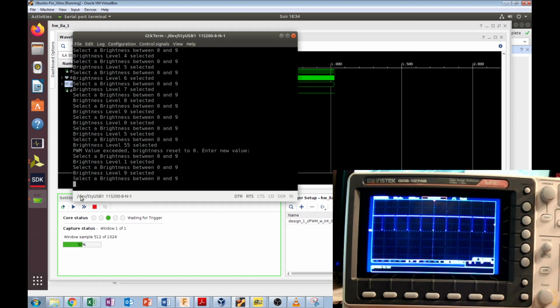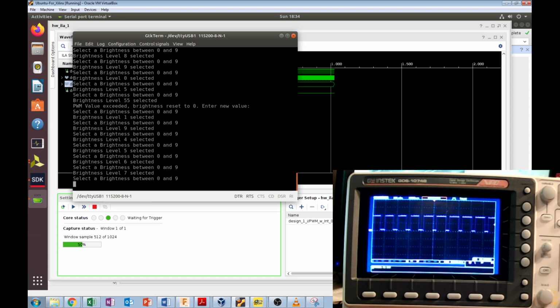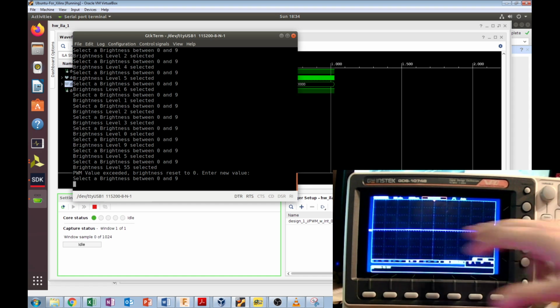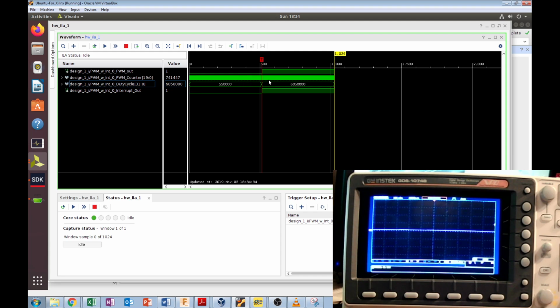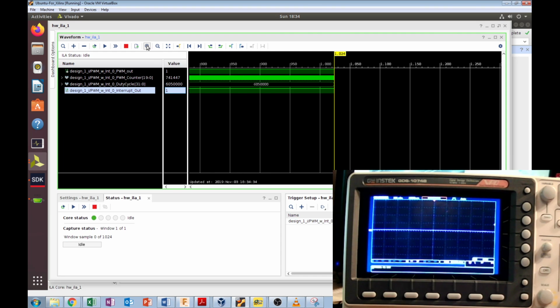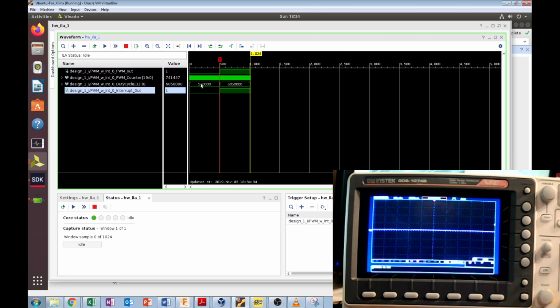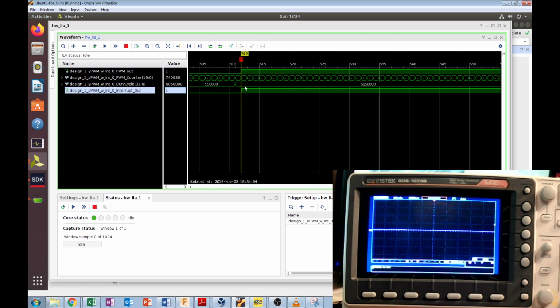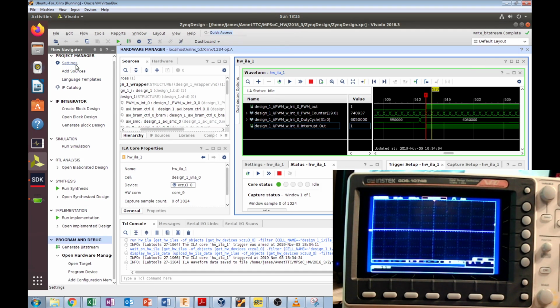And if I switch back over, I can give other good valid values in here, and as long as that's all fine, even 0 or 9, then we're okay. But as soon as I put an invalid value like the letter G, we see our trace turn off, and in the background you saw this pick up, and we see the transition. So I'll zoom in here. Oops, I click here and I can zoom in. So we can see the transition from low to high of that, and it was able to pick up and trigger on it.